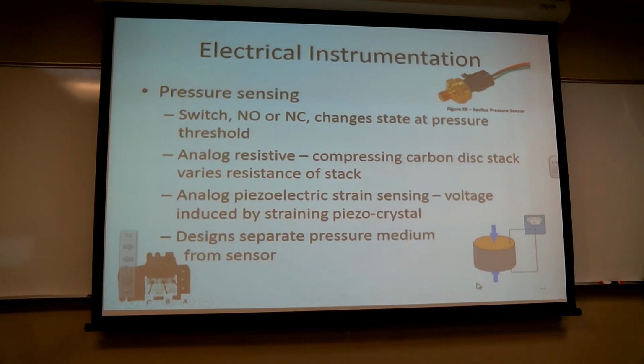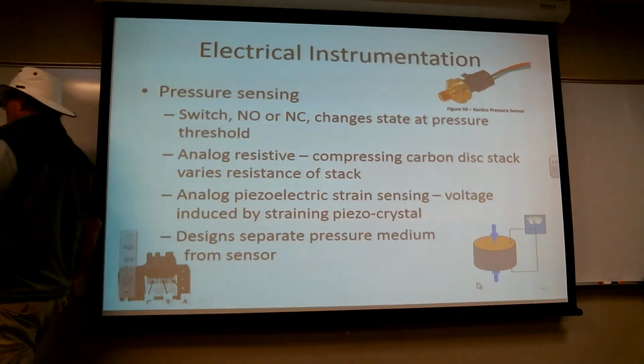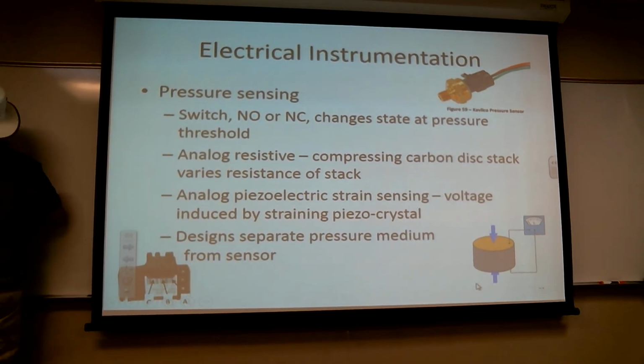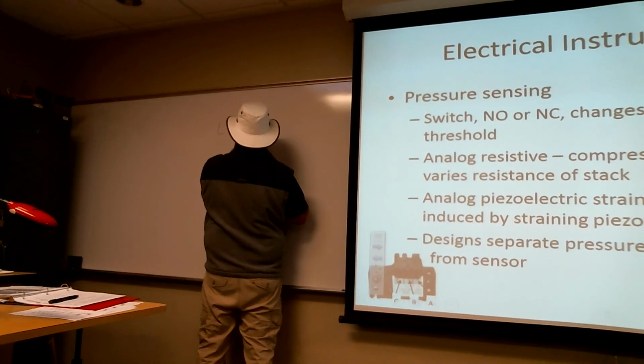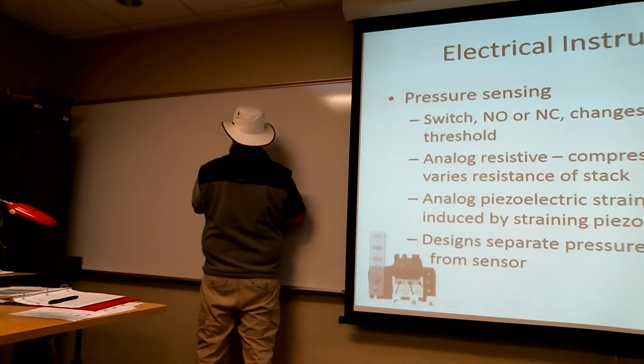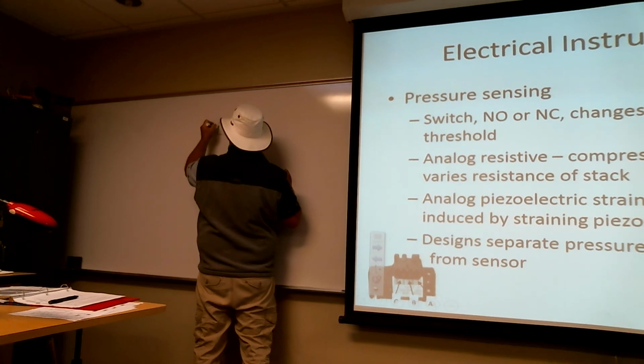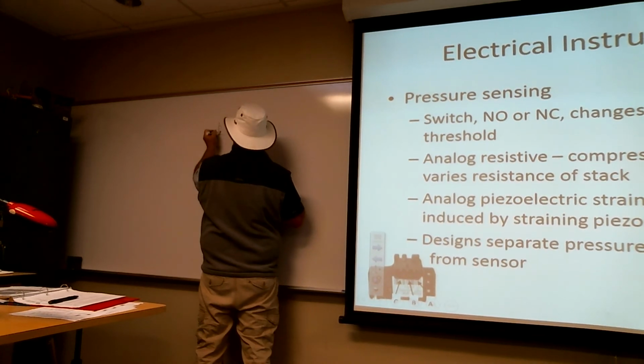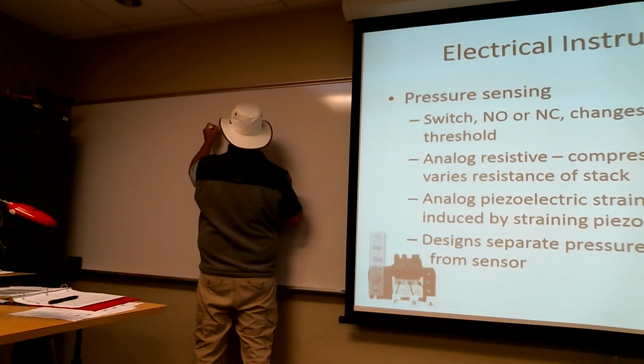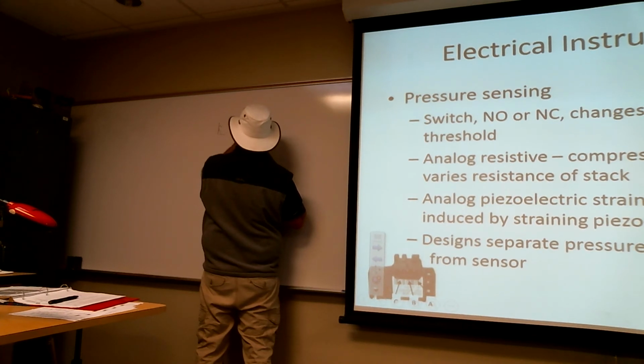We may also use the switch housing itself as part of the electrical circuit. So for example, I could take a little set of contacts, a little chamber, and feed oil pressure into here, have a small insulator in here, with a brass disc in here.